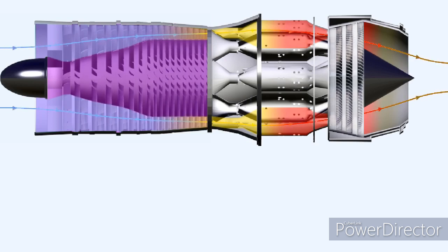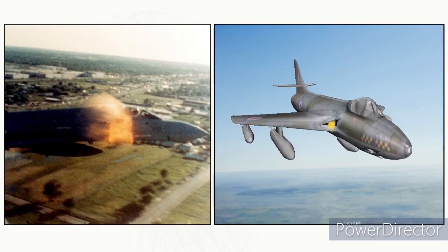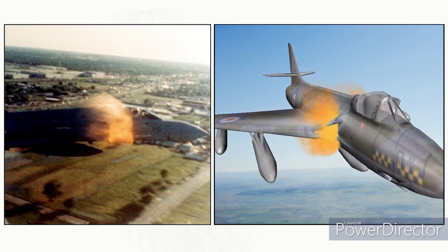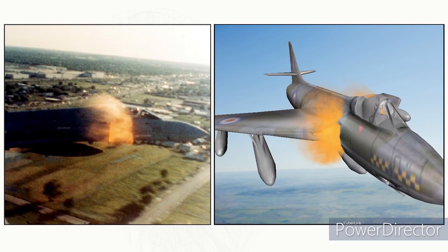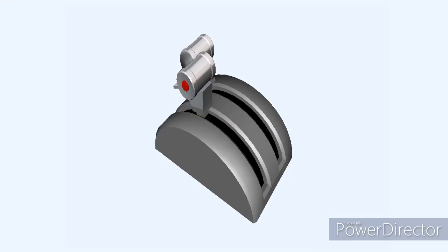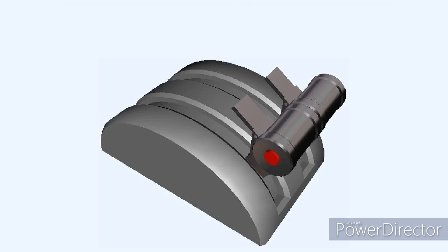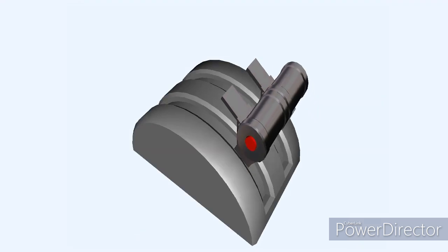The progressive deterioration of the speed of the airflow through the engine, caused by the stall phenomenon, will eventually cause a complete breakdown of airflow through the engine, which we said was called a surge. In severe cases, a surge could cause an instantaneous reversal of the airflow through the engine, with air being expelled through the engine intake with a loud bang. If surge does occur, the throttle of the affected engine must be closed slowly, and the cause investigated. Surge is most commonly caused by either fuel system malfunction or engine control mishandling.